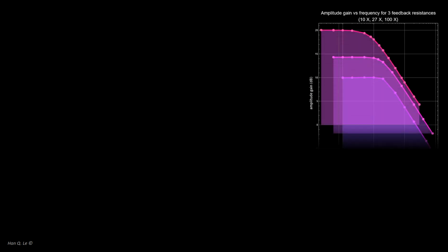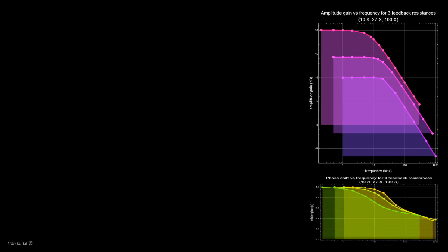Now, we can discuss what was done in Part A in the context of this Part C. This explains the use of things like Bode plots. The green line marks the frequency of interest in this case, 38 kHz. This is outside the flat response regions of the curves, known as bandwidths. Consider a low frequency within the bandwidths, the white straight line. The gains marked by the white dots follow the nominal gains of 10 dB, 14 dB, and 20 dB.